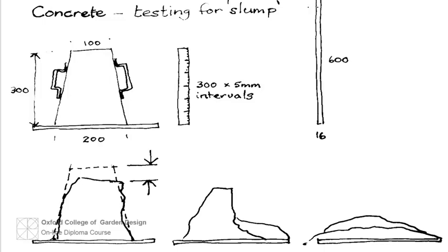Semfil is a product of a French company which produces alkaline-resistant glass fibres specifically for incorporating into concrete. It comes pre-bagged and ready to add to the cement mixer. There is no design guidance available from the manufacturers which is suitable for garden designers. A technical manual is available to engineers, and several firms produce prefabricated rocks, rock faces and cascades or stream beds using GRC.